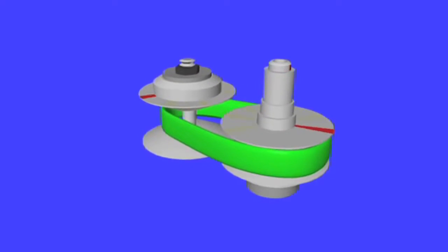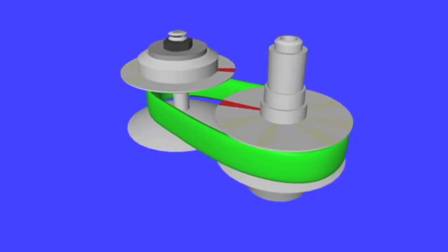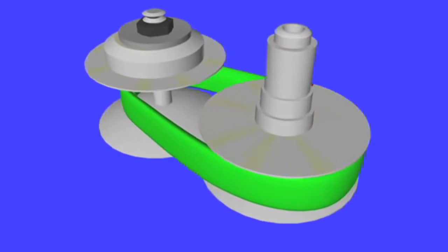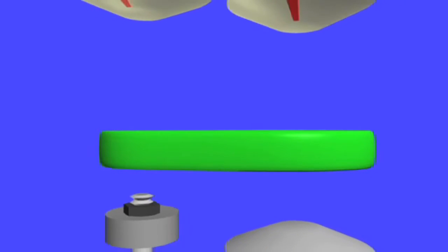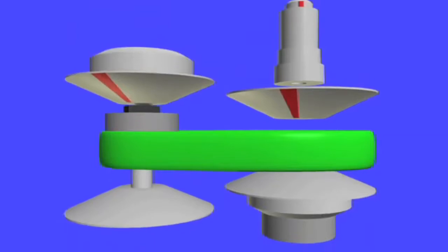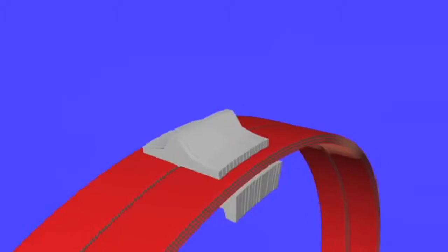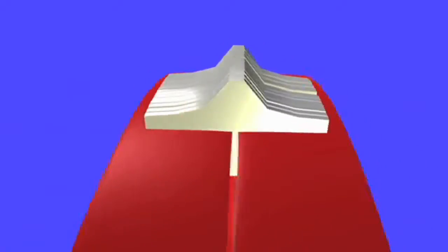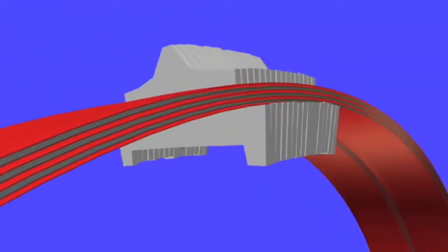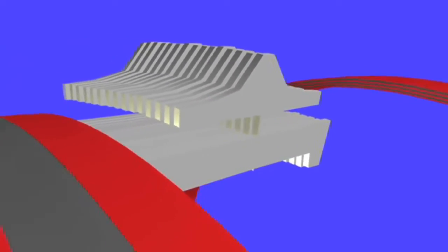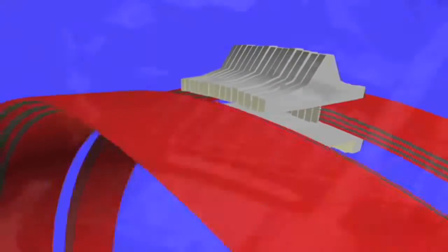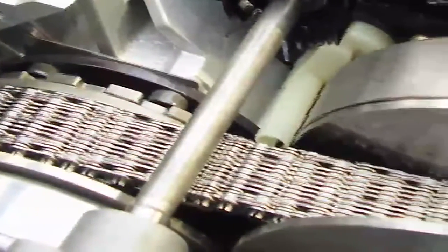Although you might not have seen one of these CVTs in your shop, it's definitely time to get ready for this technology. CVTs, in spite of all their previous issues, are the next trend for the automatic transmission industry. Multi-speed automatic transmissions, even a 9-speed from Mercedes, are being introduced every day, but they'll never achieve the infinite number of ratios found with the CVT. There are a few things the CVT might not handle well right now, including weight and high torque capacity. But don't be surprised to see these CVTs even in light-duty trucks in the future.